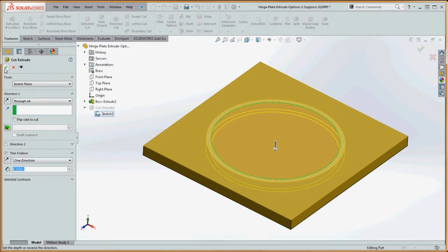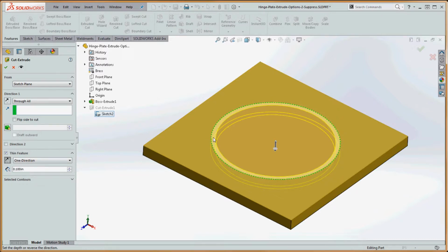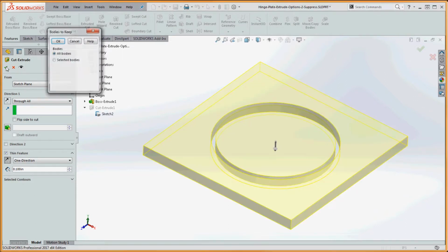If we just go to the green check mark here, by the default settings it's going to give that thickness of that line 1/10 of an inch. You can see its preview in here. And it's going to go off in one direction, which is going to be from that line, which is the dotted green-yellow arc in there. And it's going to go off to the outside. But if you click the arrow in here to reverse direction, now it's going to go on the inside. So just for the fun of it, let's just see what it does.